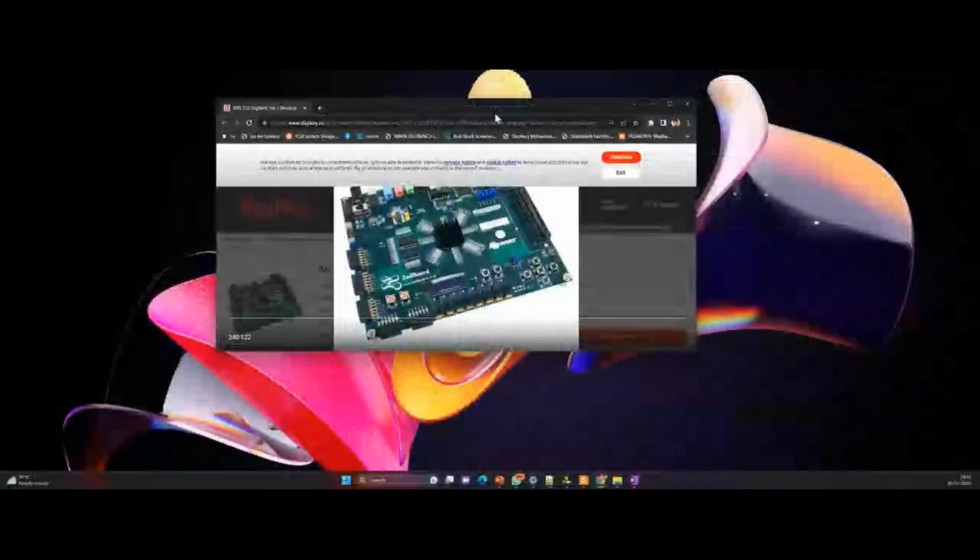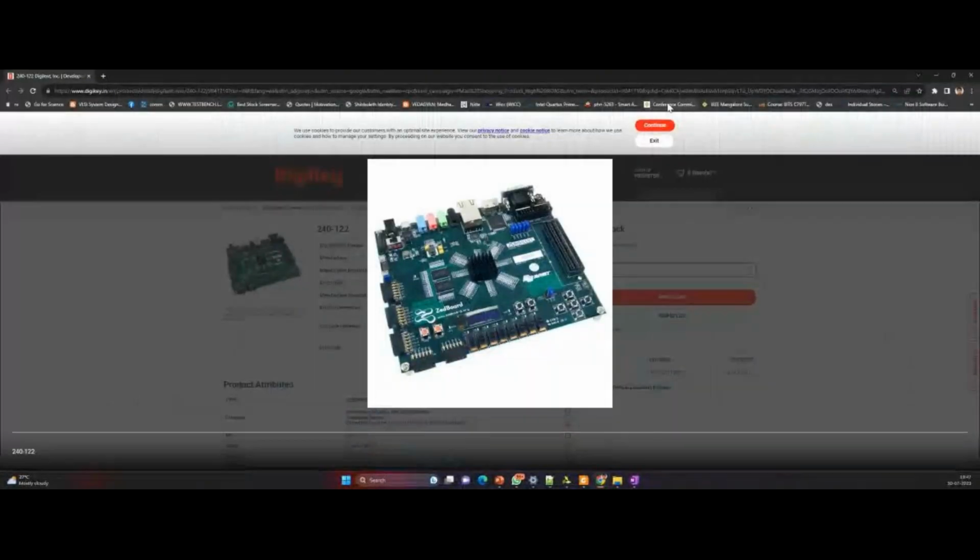If you consider this image, you can see under that heat sink is the FPGA. Through the JTAG cable, you program this FPGA for your circuitry. Whatever LED you have connected or whatever input you are giving, this FPGA will act like that circuit. Later, if you want to reprogram through USB or JTAG, you can just reprogram this FPGA and make it that circuitry, and all the hardware will work accordingly.